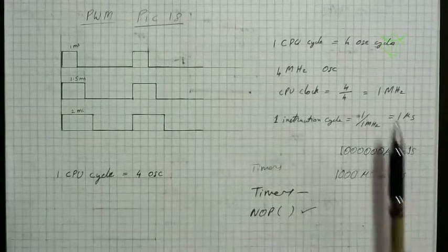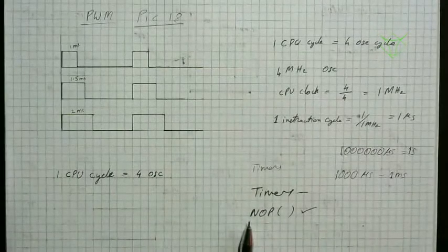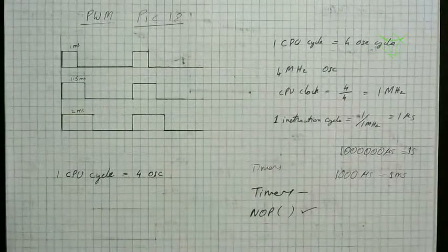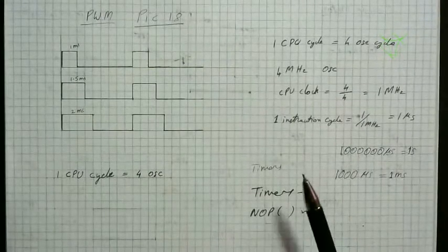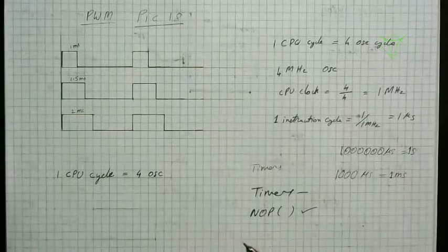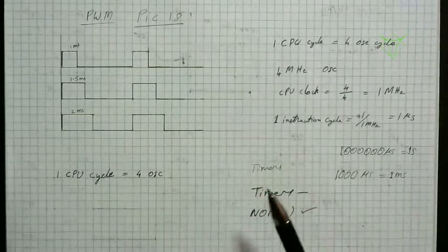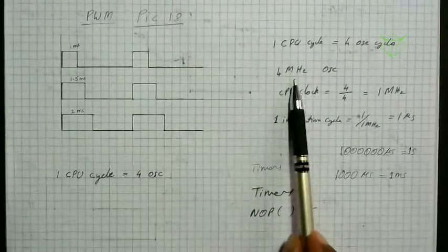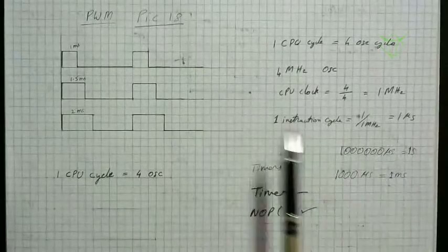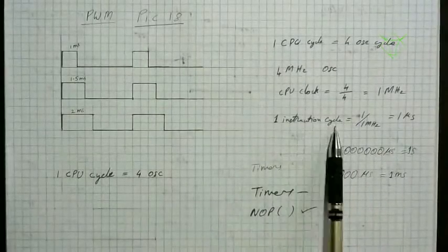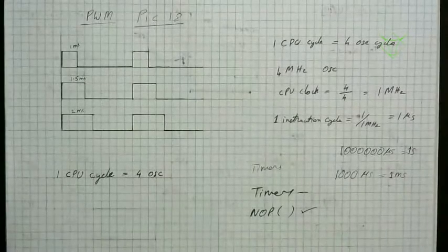So this is about the theory. In other microcontrollers like ARM and AVR or ATmega from Atmel, you don't have to worry; they work at whatever clock speed you have connected. Then you have to waste 4 clock cycles, so the calculation remains the same. You have to find the instruction cycle and waste so many cycles to get the delay you require.